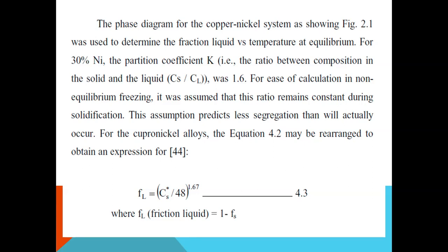For ease of calculation in non-equilibrium freezing, it was assumed that this ratio remains constant during solidification. This assumption predicts less segregation than will actually occur for copper-nickel alloys.